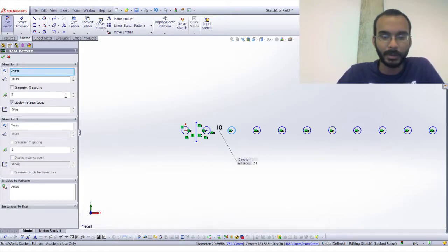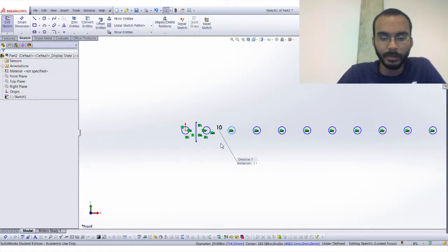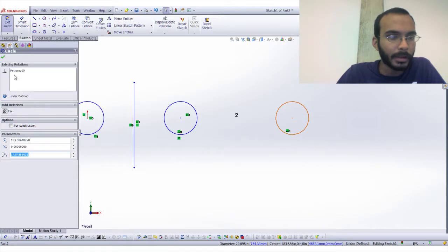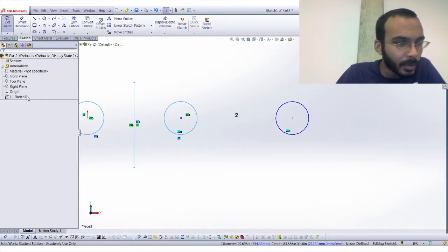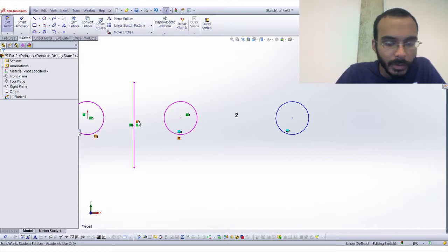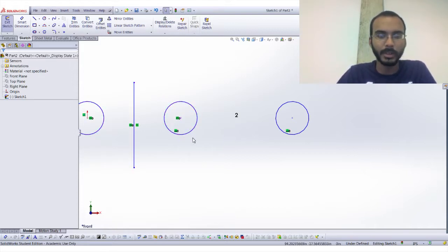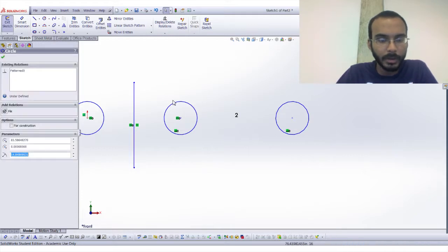You can drop it back down to 2 and it'll basically fix where your parts are and things like that. A lot of times being able to come in here and right click on things helps a lot. Same with the mirrored part, it doesn't let you do that, which it should, but it doesn't, which is kind of annoying. So once you mirror something, I don't know if there's a way to edit it inside of a sketch mirror. You can delete the relation and tell it it's no longer symmetric, but there's no way to just change what is being mirrored.